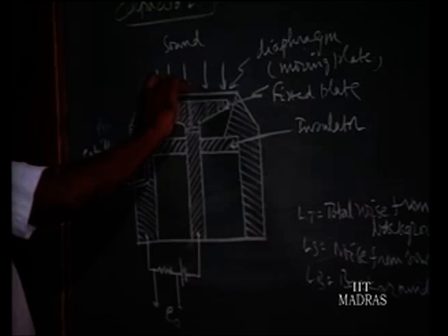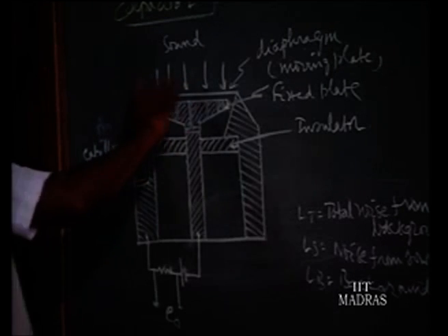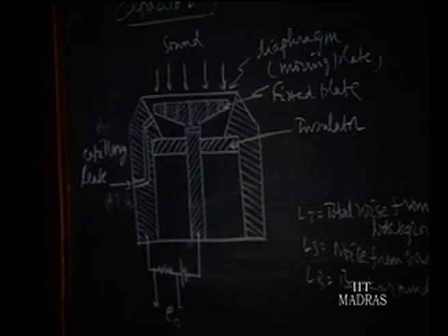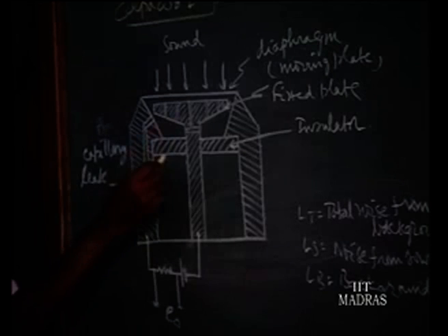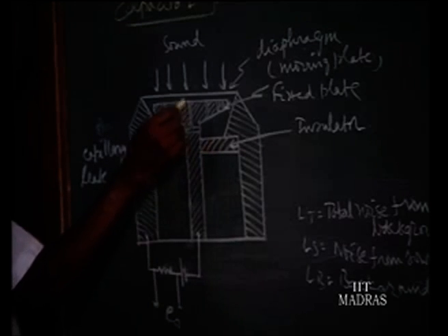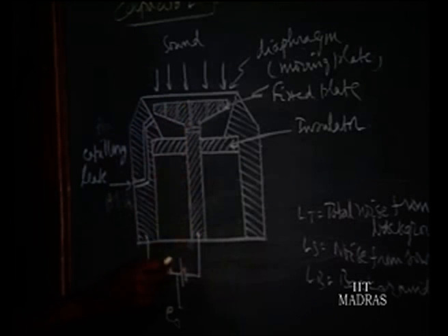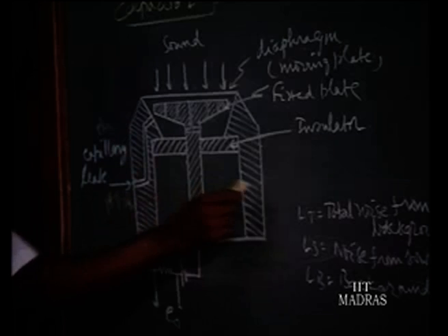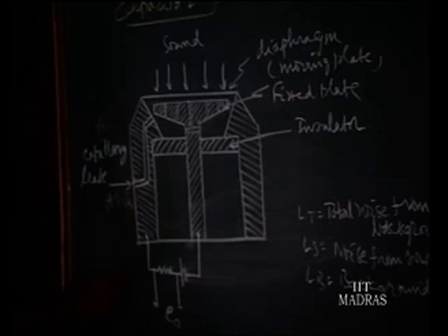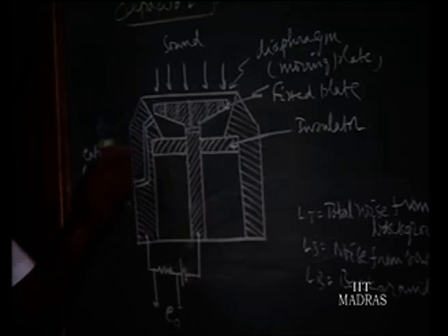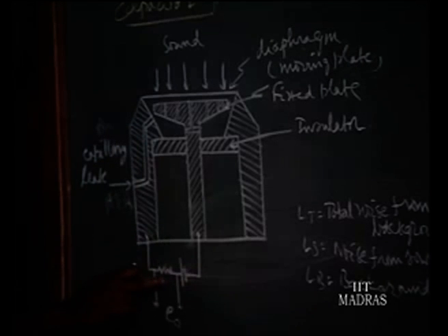So, now this is a capacitor where the distance is varied due to the vibration of the diaphragm, and you find with an insulator these two plates are separated, and the center piece as well as the housing outside, which is metallic housing where the diaphragm is fixed, is connected to a battery through resistance R. So, it forms a full circuit, a simple circuit with a single capacitor and a constant resistance.